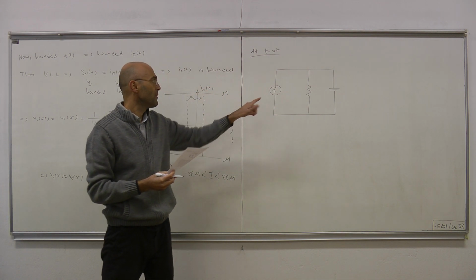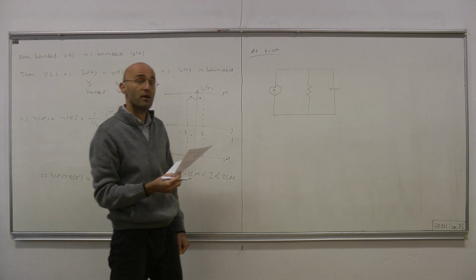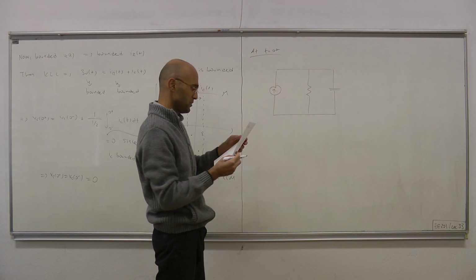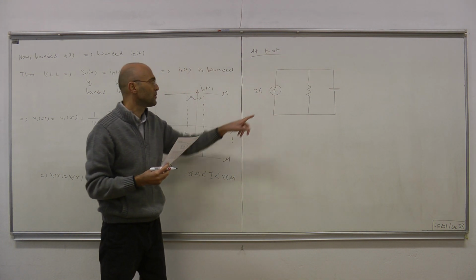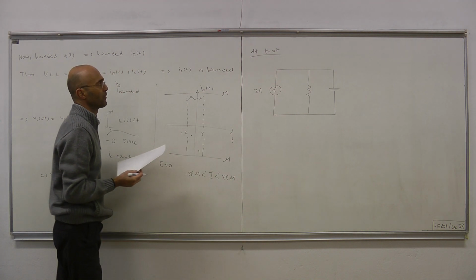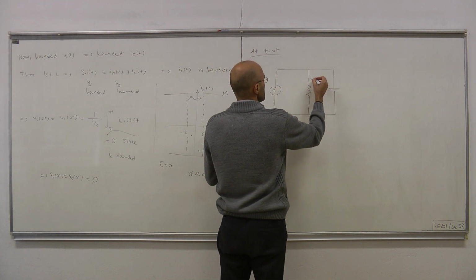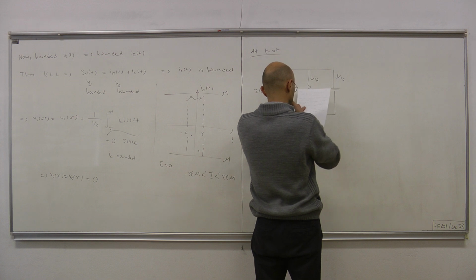At that particular time, this provides 3 amps of current, because it provides 3 amps at any positive time, and 0 plus is by definition a positive time. Therefore here we have 3 amps. We don't have to write 3 ut. This is IR. This is IC.